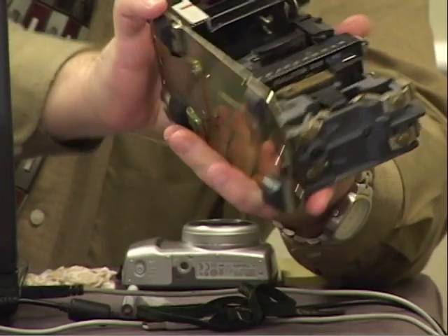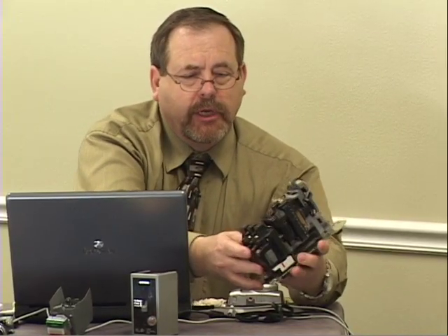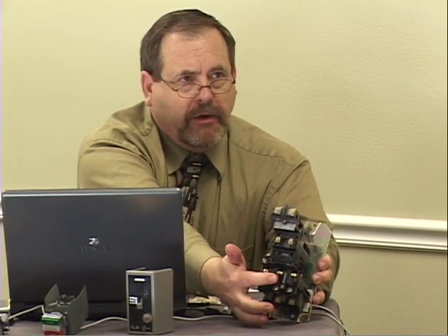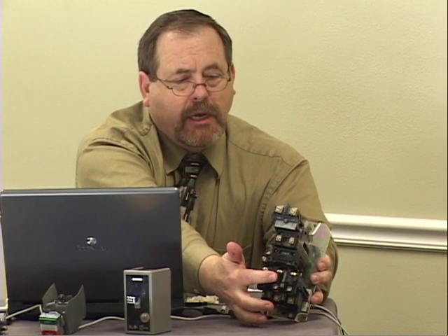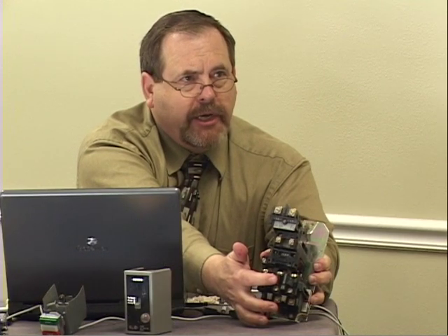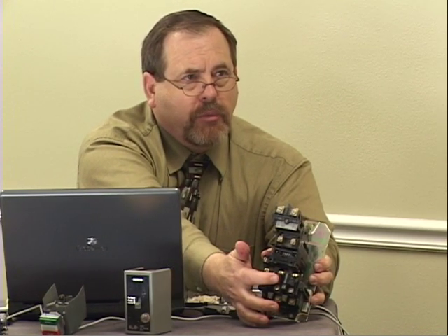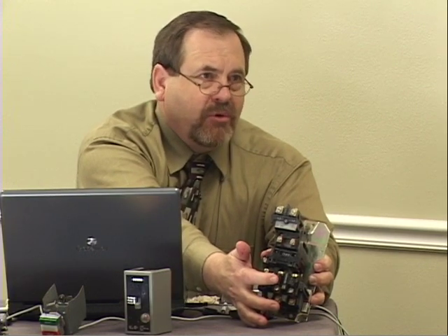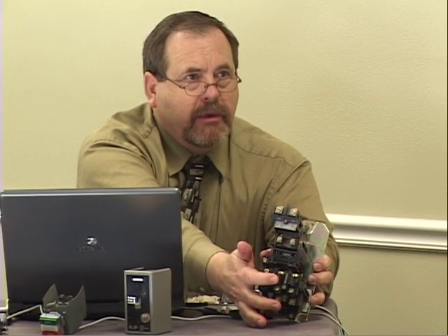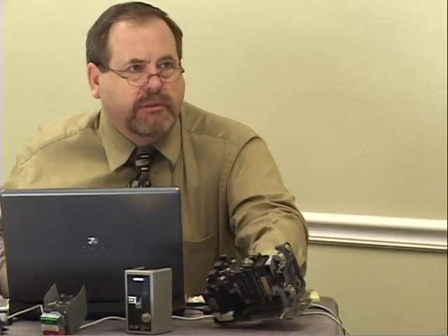Got it. Okay. And then you started to bring up another comment, Mike, about the difference between contactors, starters, and relays. Of course, the difference between a contactor and a starter is this overload block here. If it didn't have this overload block, it's just a contactor. And the difference between a relay and a contactor has to do with the amperage, and that might vary with manufacturer, but usually at about 30 amps it becomes a contactor instead of a relay. Also, with multiple poles, a relay can have several poles, like 3 or 4 poles, but if you have something where you're switching like 12 poles, then it's going to be a contactor, not a relay. The principle's the same, it's just a sizing situation.